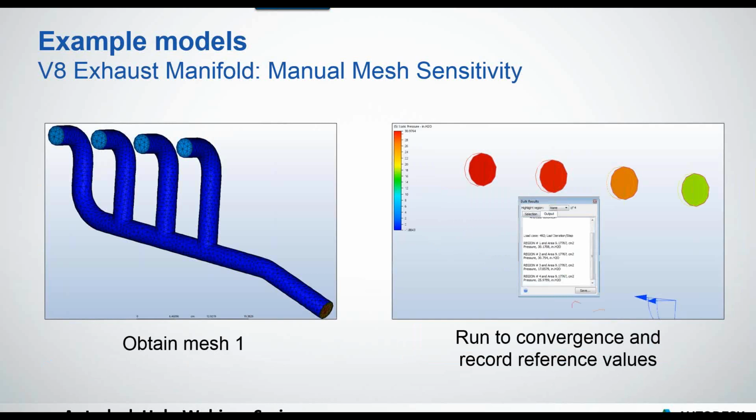So I did a manual mesh sensitivity study. On the left was my mesh 1. I actually didn't take the best route here. I only auto meshed this, which I really should have just hit auto mesh and then enhanced it. Anyway, all it ends up making me do is have more scenarios and more tests. I ended up doing 5. Usually you can do less. It's just that my baseline was really coarse.